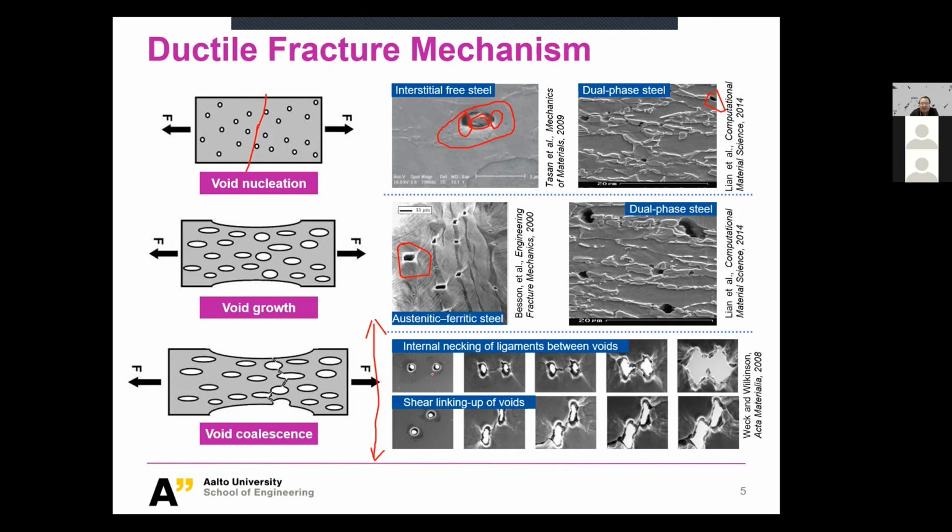So in the first case, the voids are going to develop ligaments that connect to each other. You can see when we go with the deformation, the voids are getting bigger, but something is developing between them. You see, there is already something there, and this is another one. And finally, these two really get in touch with each other, and it becomes a really big one. And this is so-called void coalescence.